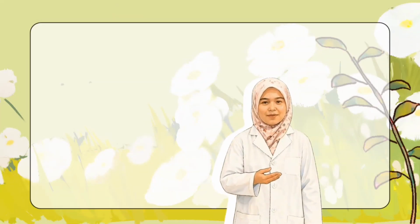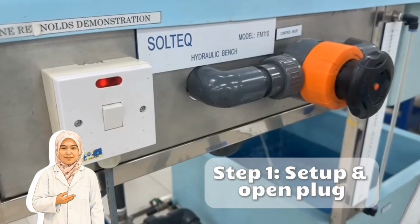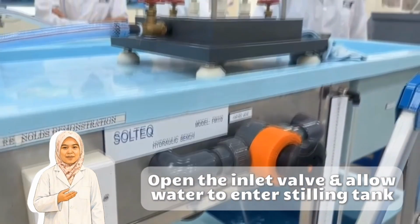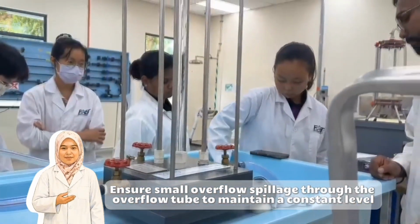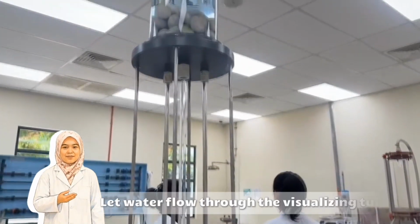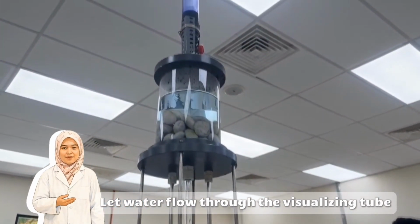So here I will explain the procedure, which has 4 parts. The first thing is the initial setup. The water valve V1 was opened and the water was allowed to enter the settling tank, and a small overflow spillage was ensured through the overflow tube to maintain a constant water level, and the water was allowed to settle for a few minutes before the experiment began.